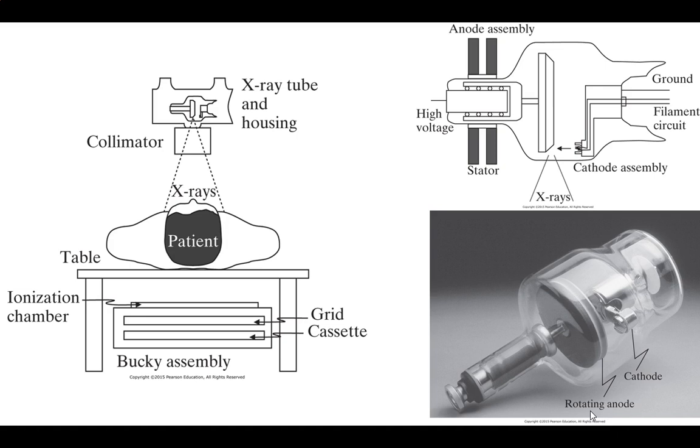This is going to produce electrons. We're going to make them move really fast and slam into this. What we don't want is something in the way of our electrons. So imagine I'm making an electron gun effectively here. Air will disrupt the path of your electrons, so you've got to evacuate it. Otherwise something blocks your electrons and they scatter all over the place. They'll still make it down here because they're attracted to this, but it will no longer be a nice tight spot. So it'll have all kinds of problems, and then the air will heat up and more problems can happen. So we have to get rid of that air so we get a good, clean, functioning tube.